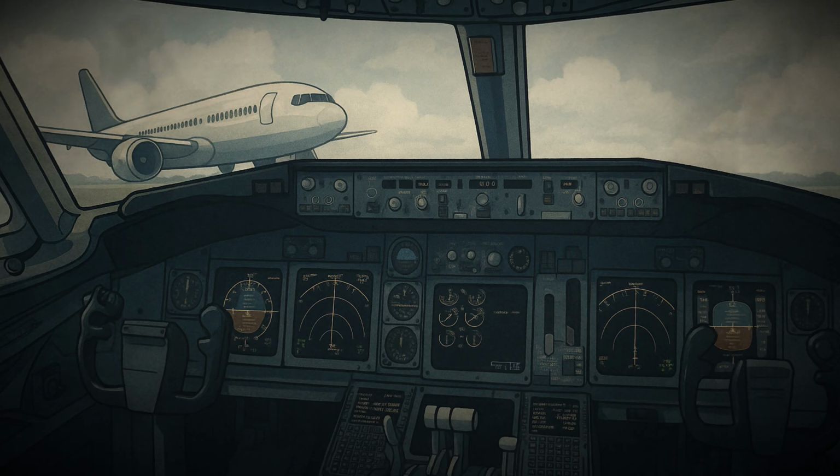Wave drag becomes significant when airplanes approach the speed of sound. At transonic speeds, shock waves form on the wings and fuselage as the air is compressed and accelerated. These shock waves create a sudden increase in drag, which can make flight near the speed of sound inefficient and unstable. Supersonic and hypersonic aircraft are designed with special shapes, such as swept wings and pointed noses, to manage shock waves and reduce wave drag.